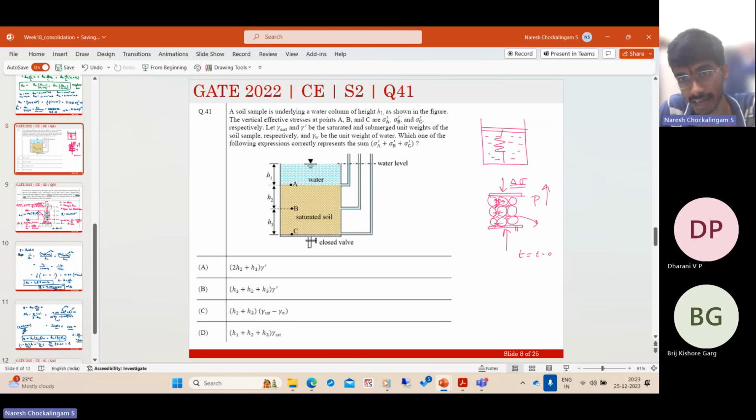So this is given by this simplified model. You have a spring inside a container, and you also have the applied force. When we initially apply the force, if there is no drainage, all the pressure will be taken up by water because of equilibrium, right? Water is incompressible, so the force on either side should be equal. So water will take up all the pressure.